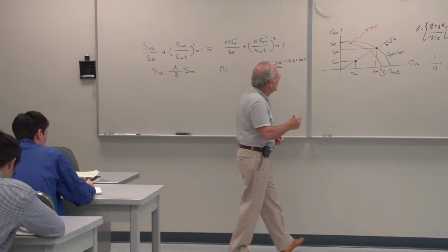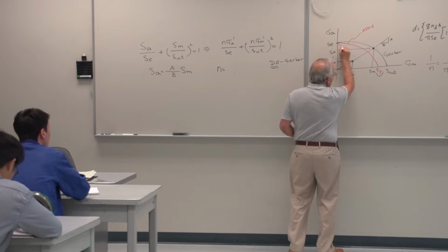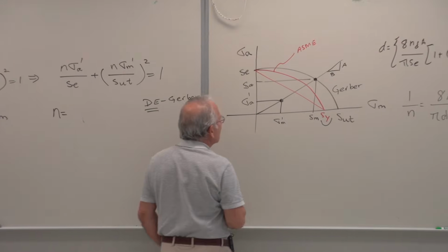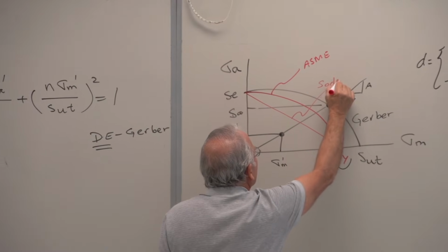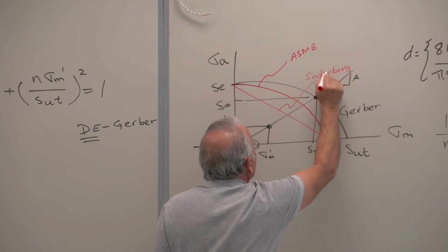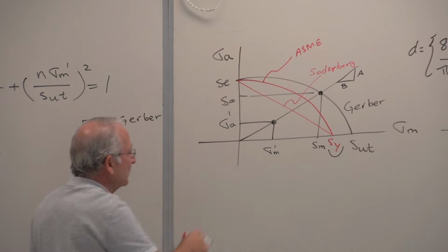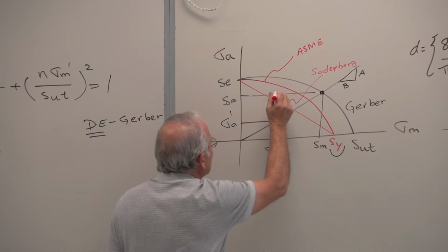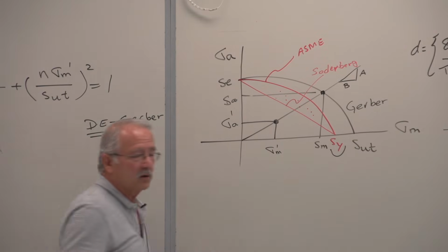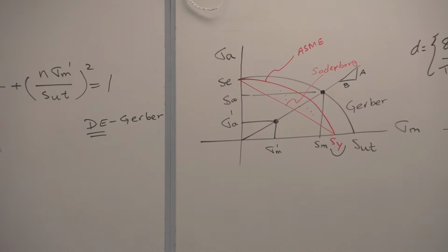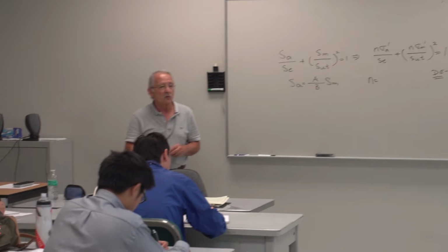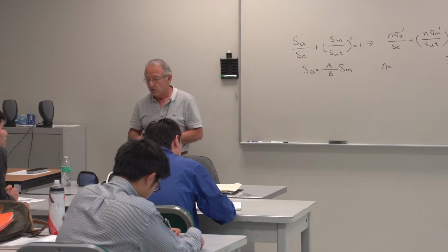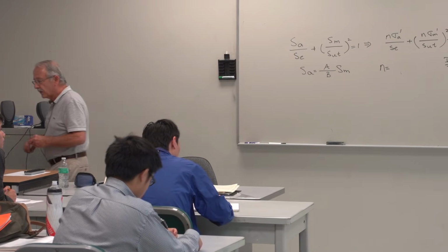Yes, you can, but the linear equation comparable to ASME would be this. This is the Soderberg. The problem there is that you will be missing all of these areas. The ASME, the elliptic is used extensively in industry. It's the actual equation that's used a lot in industry for fatigue analysis. Any questions?